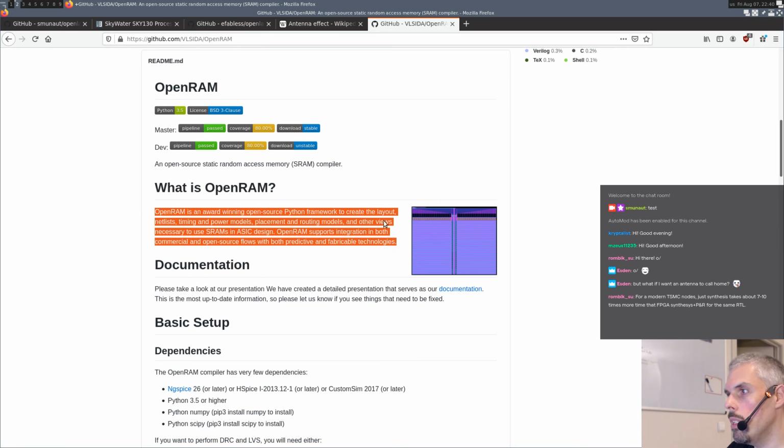So the way you'd basically implement that using only two ports is you replicate the RAM, right? Because even in an FPGA you don't have three-port memory. I don't know any FPGA that has that.